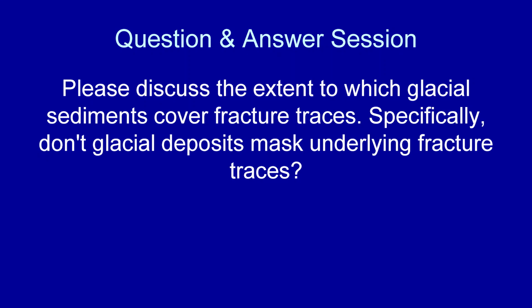We are somewhat amazed that you are able to pick up fractures beneath some areas of till. Now, if you're talking 200 or 300 feet, the likelihood is that it is going to mask it. However, you may be able to determine a linear feature, and then nothing is shown, and then on the other side of a valley where there's a thinner overburden, it picks up again, and you can surmise that those two straight features are connected beneath the area where it becomes difficult to identify a specific linear connection.